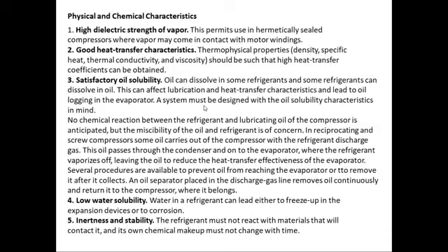If it is mixed, then as the refrigerant travels throughout the refrigerating circuit, after the compressor it goes to the condenser, then the expansion valve, then the evaporator, and then back to the compressor. Oil will follow the same route and come back if it is soluble. If it is not, then it will stay either in your condenser or in your evaporator, wherever it gets to.